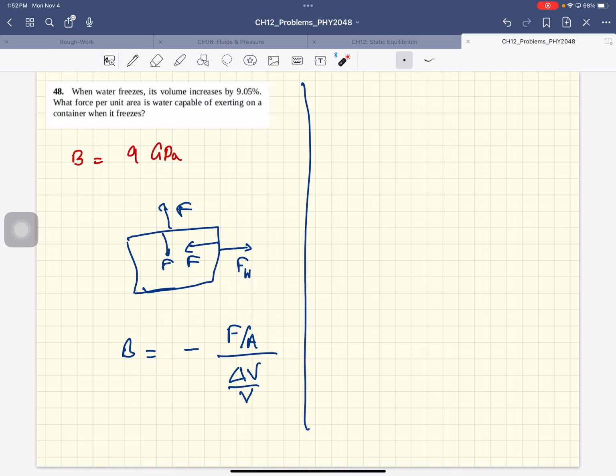Remember, for a given load, there's the elastic limit. You want the strain to be way less than that, okay? And that'll determine the stress. And the force is fixed, so the thicker the rod, the less the stress, okay? So that's what you're trying to do.